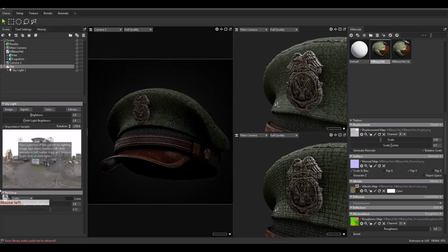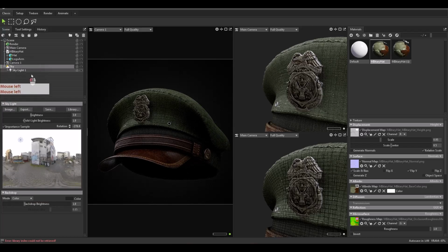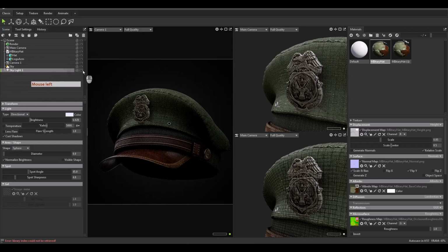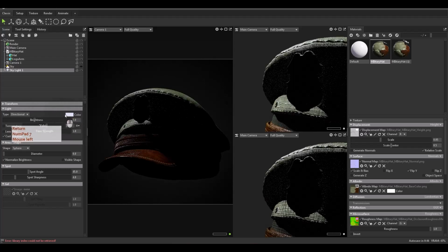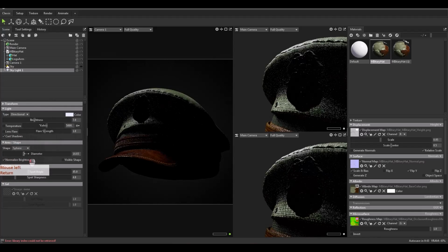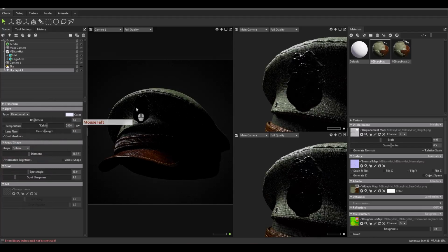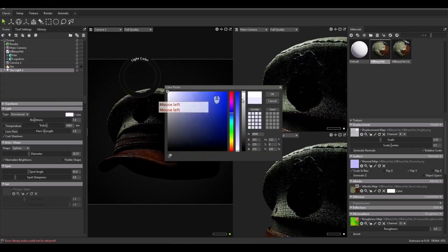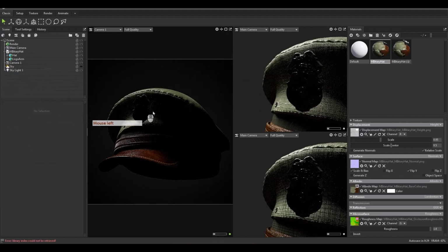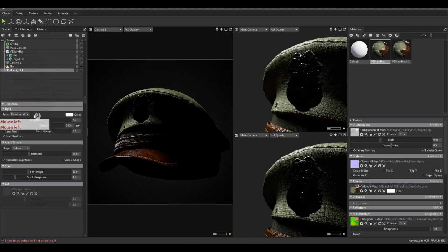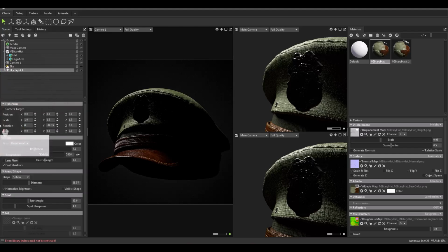So I just click in here and detach this light from the sky and turn off the light from the sky. So I'm going to increase the light amount to 7. That's it. And increase the diameter from shape to have some soft shadow and create the pure white light. So this is my light that comes from here. So I need to reset the transform. Okay.